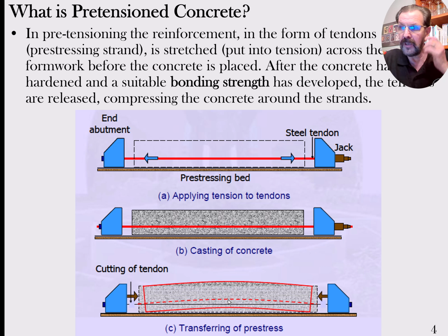With post-tensioning, you most often end up having to have custom-made cables with an anchor built on one end and a tail sticking out, and a bunch of hardware that you deal with there for each individual beam. In pretensioning, we often might have a form that goes 600 feet or something like that down the line, and you have a whole bunch of beams in line using the same cable, so you get some efficiency by putting a whole bunch of beams in the same long form, and you just have bulkheads dividing them up all the way through it.